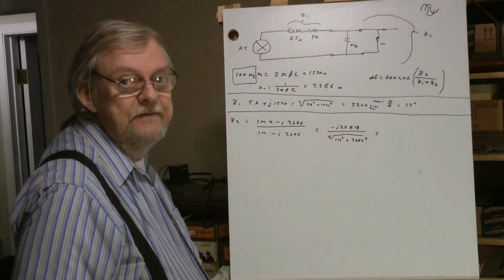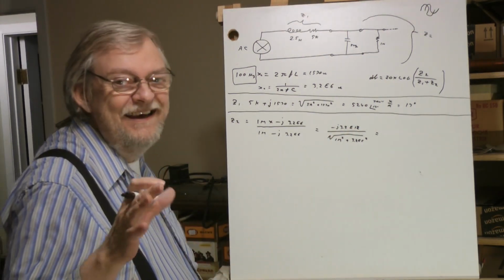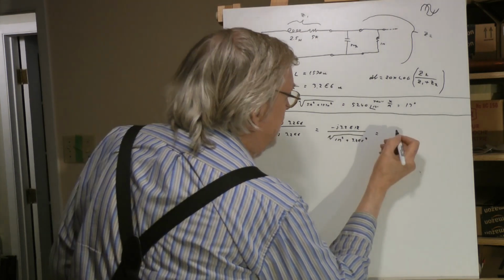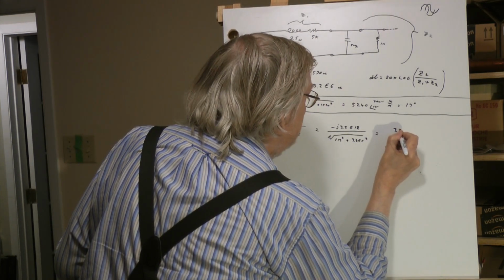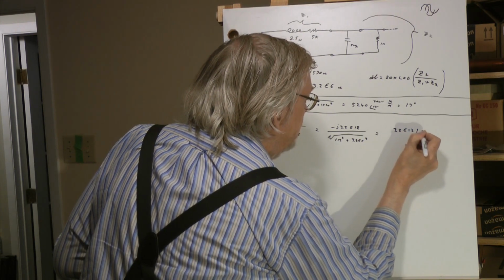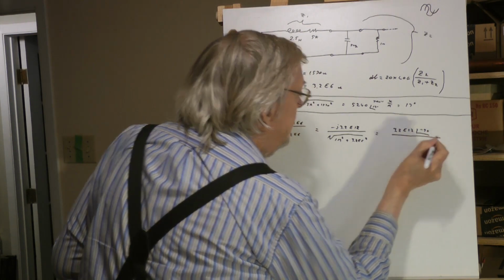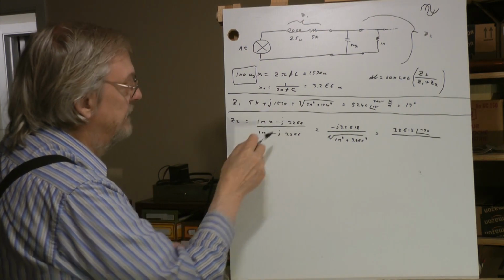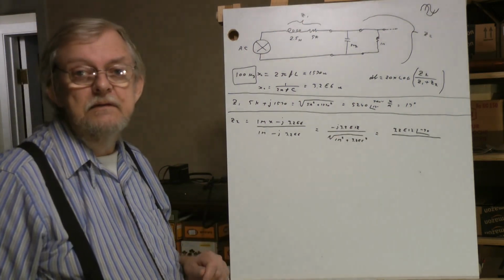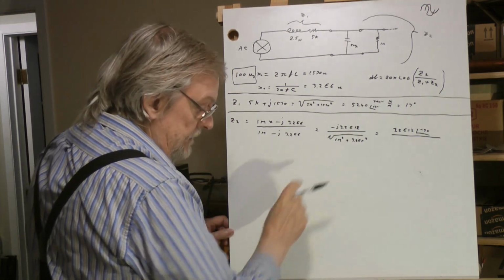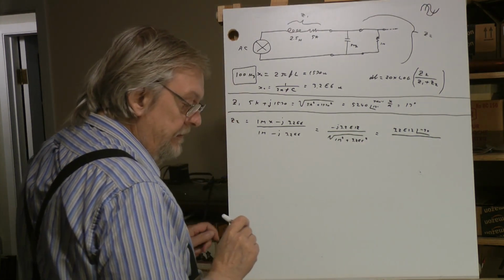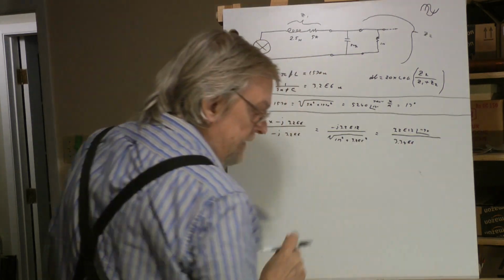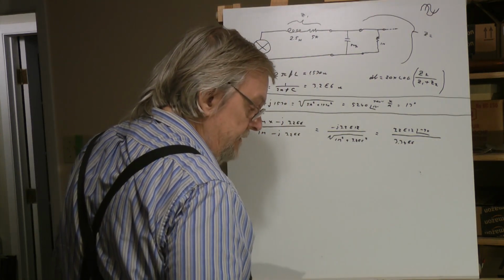And we move along to, you can't have a negative resistance, obviously. Well, you can, sort of in theory, but we get rid of that minus J. We change that to a magnitude, 3.2 E12 at an angle of minus 90 because it's purely capacitance. That part of the formula. It's a capacitor multiplied by 1,000,000, so it's a big capacitor. Capacitor is minus 90 degrees. The bottom part, the Pythagoras, ends up being 3.34 E6. 3.34 E6. And its phase again, of course, is the